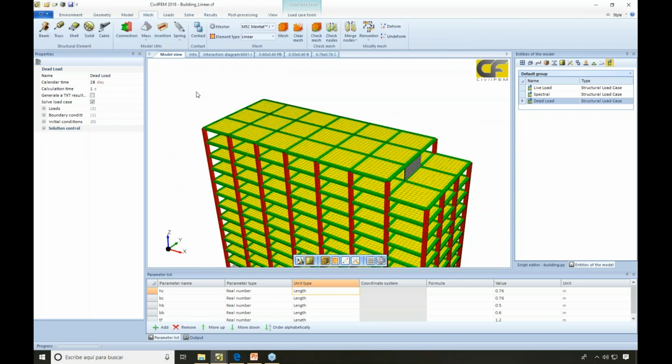I didn't mention that after the mesh, we can always change any property using model utils, creating springs, adding masses, or creating insertions. Insertion connections will define a kind of tie-ins of degrees of freedom, and a very useful util is the connection.